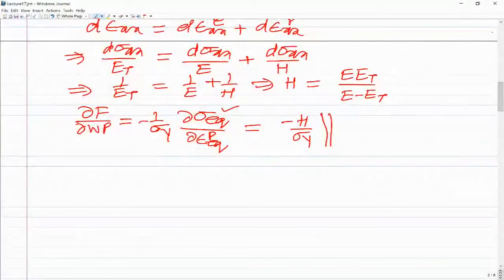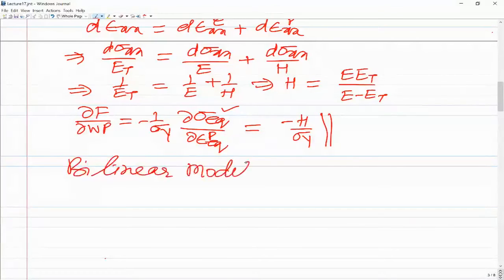Usually in the software, the most common models are, of course, there can be a general nonlinear elastoplastic curve. The sigma equivalent versus epsilon p equivalent curve could be a general nonlinear curve, but sometimes this is simplified by what is known as either a bilinear model or a multilinear model. In the bilinear model, the whole stress strain curve is in terms of two straight lines.